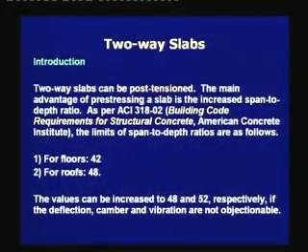Two-way slabs can be post-tensioned. The main advantage of pre-stressing a slab is the increased span to depth ratio.